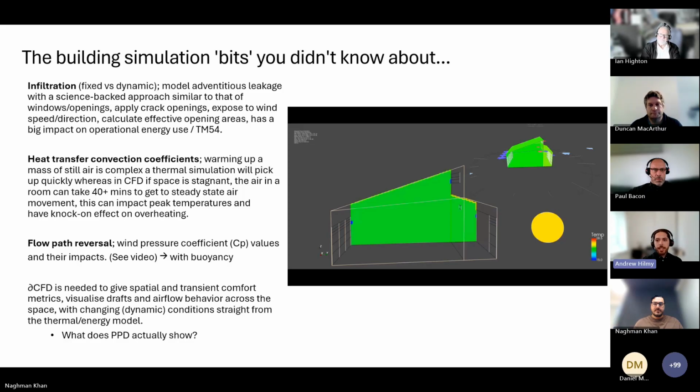So definitely the worst way to model infiltration is with the static air change rate. The next best way is with this and the wind-driven infiltration. And then, of course, you could do wind pressure coefficient files, but we found that it's diminishing returns, and that our default model for wind pressures is very close to what you get when you do a full external CFD simulation anyway.